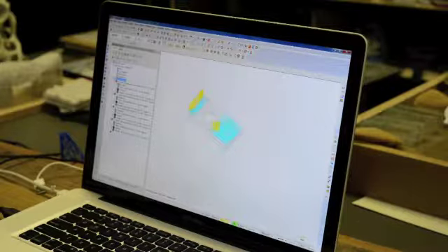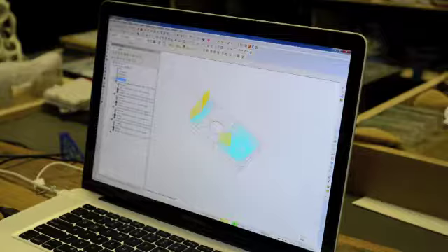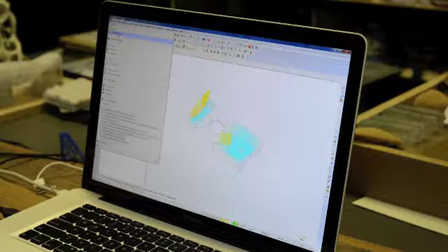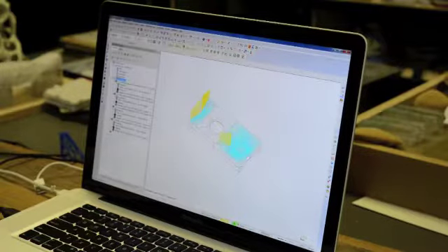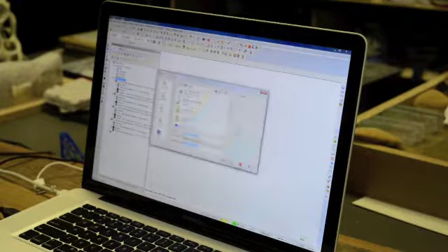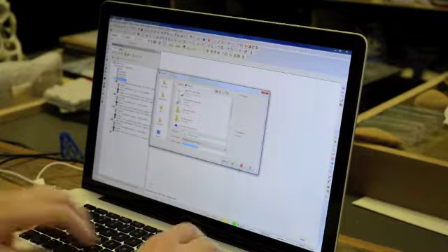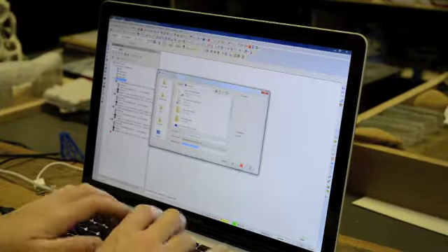Okay, so this part that we're milling is double-sided, and the easiest thing to do is a file merge / pattern, and when we do this, we can basically preserve all of our tool paths, or tooling parameters that we've set up, and we just delete this existing geometry and do a file merge. But first do the save as, and we'll just give this name bottom.